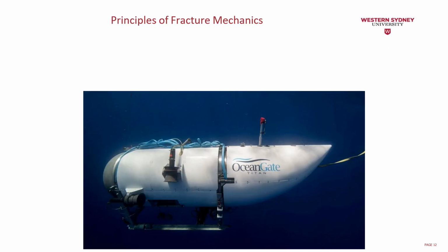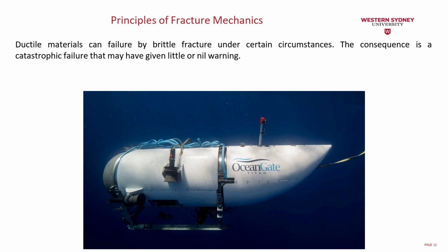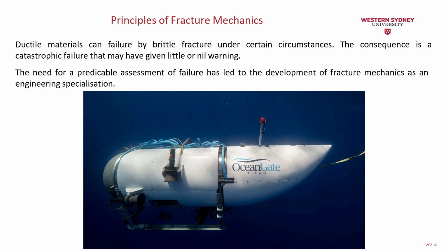So, the principles of fracture mechanics. Ductile materials can fail by brittle fracture under certain circumstances. The consequence is a catastrophic failure that may give little or no warning. The need for predictable assessment of failure has led to the development of fracture mechanics in engineering specifications.